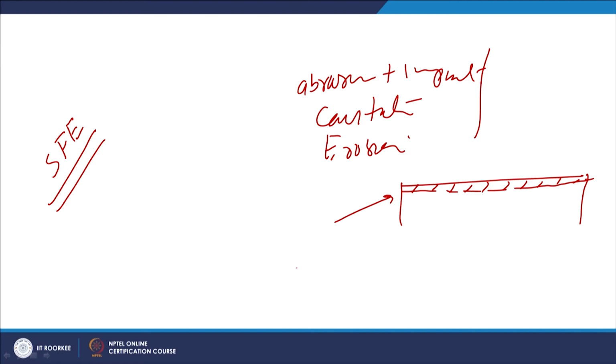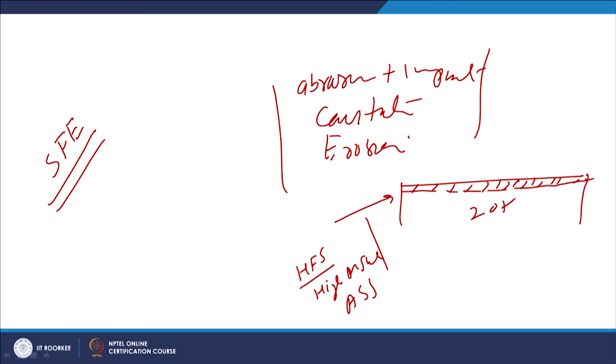So, metals like Hadfield steel or high manganese steel show low stacking fault energy. Even austenitic stainless steel shows low stacking fault energy, and so a good work hardening tendency under impact conditions. Once the material surface is hardened, meaning hardness increases from a low value like 20 HRC to say 60 HRC or 50 HRC due to the impact during service, it enhances the resistance to the removal of material by these wear mechanisms.